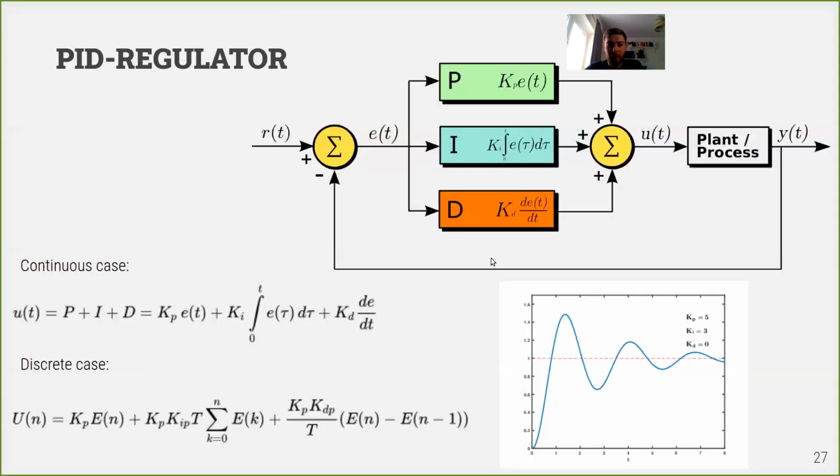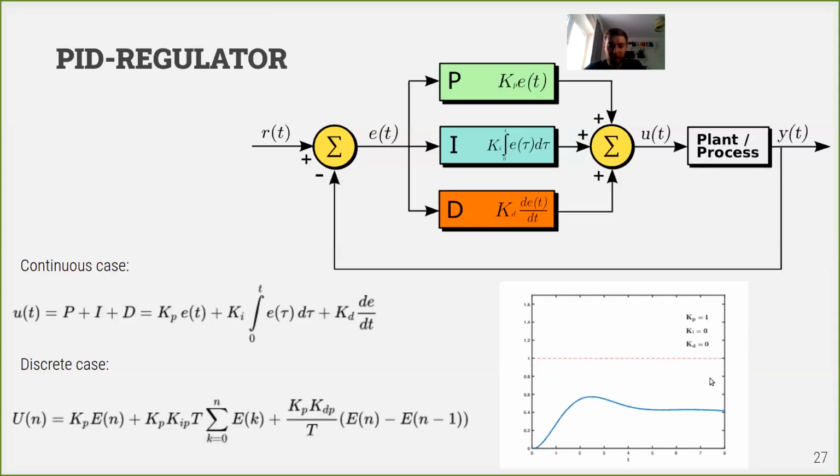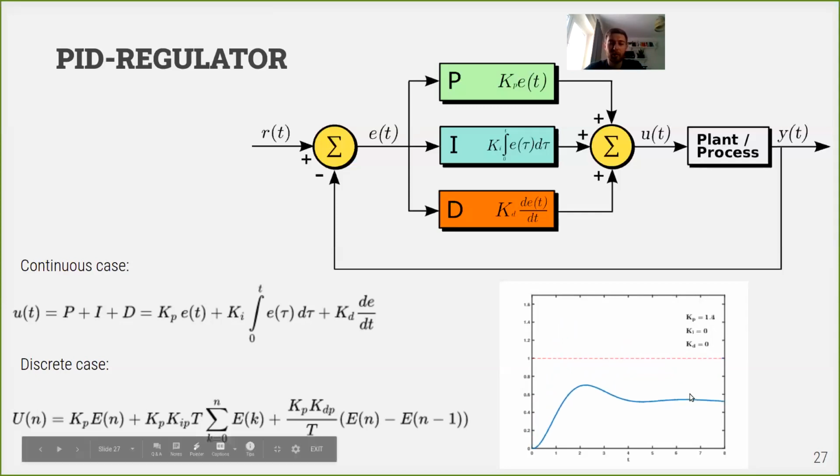So imagine with a PID regulator, we are controlling car speed. And of course, we don't want to run these experiments setting up these coefficients with a real car, because it's just expensive. We can break things down. You remember that with a huge overshooting, we just can break our motor. And that is why these methods should be applied to some model of an object, because if applying to a real object, trying to play with these coefficients can lead to destruction of the system.